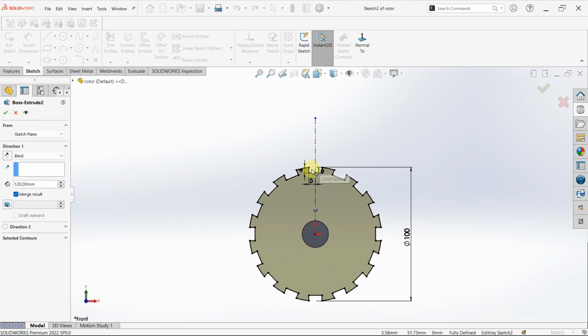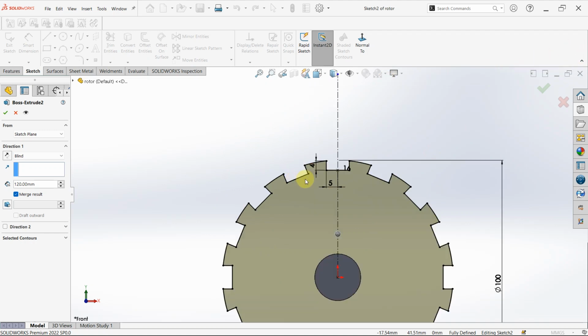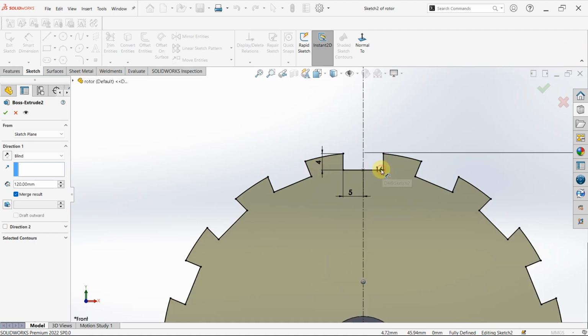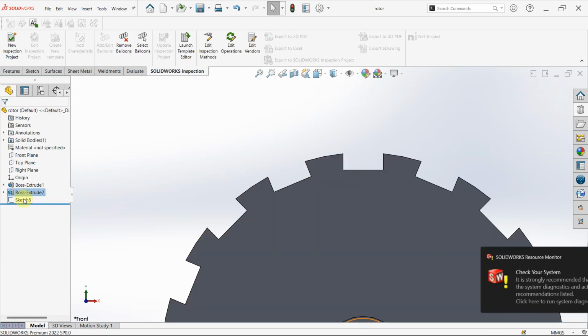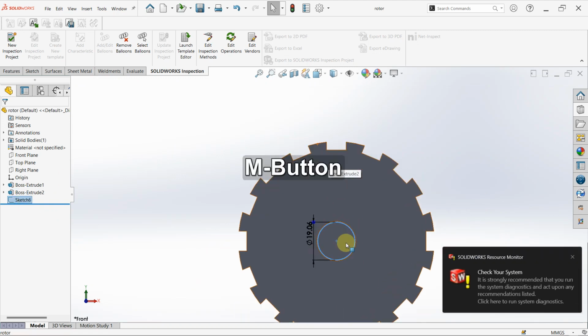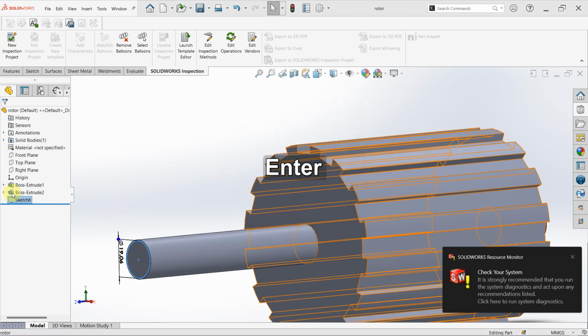After sketching this side and this side, I used the circular sketch pattern tool for all the other ones. This one is 16 times, and this one is 4 mm. The height just defines the position of this, and then I recorded this with the circular sketch pattern, 16 times. That's what produces this pattern. And then lastly, this sketch is not there.